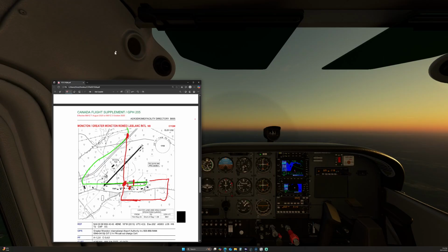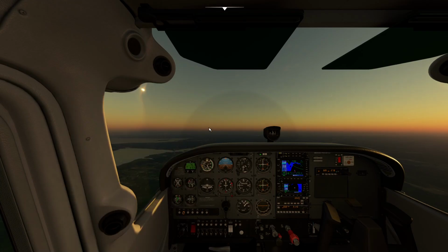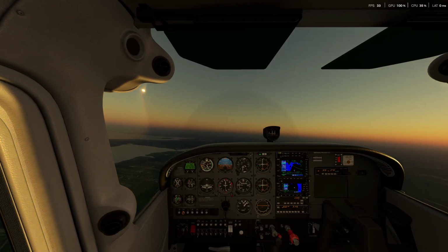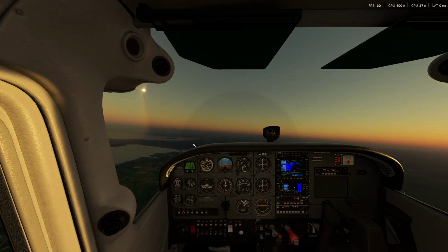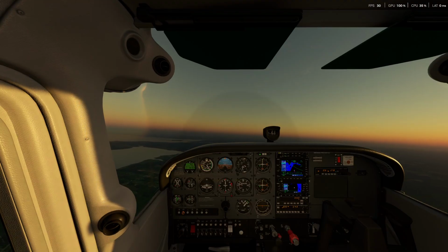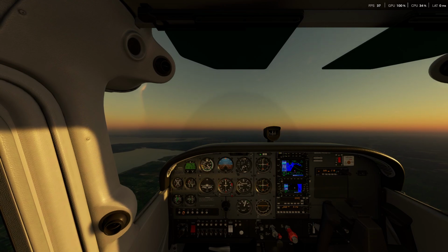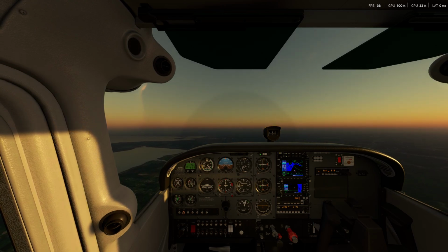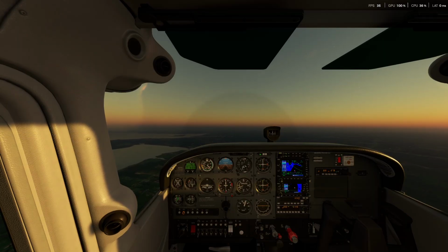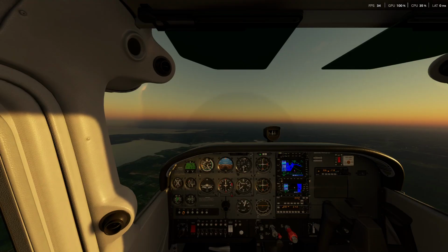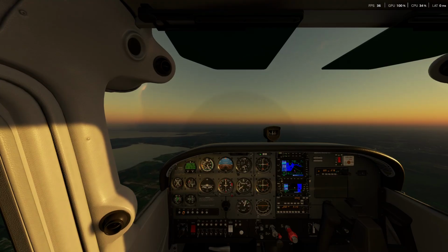Alright, so I'll go ahead and take that away. So we can start our descent here shortly. So we'll do the descent here. Alright, so we'll take back about 2,100 RPM. And we'll do a cruise descent here to about 2,000. Alright, so I'm just trimming out for about a 500 foot descent rate. And we'll do the descent checklist here.